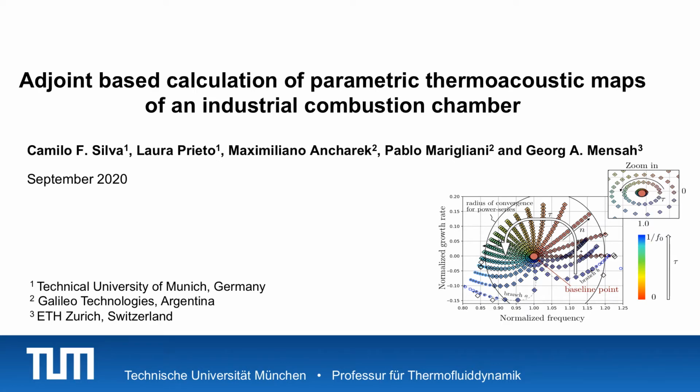The idea of the work is to show you that by using high-order adjoint-based perturbation theory, it is possible to compute what seems to be very complex and expensive parametric thermoacoustic maps in a very efficient manner.